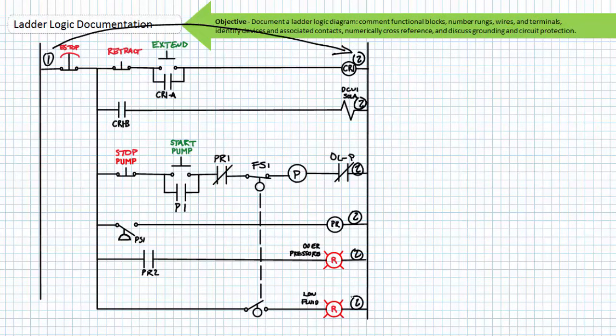All devices attached to this common connection are assigned the wire number 2. Note a number of different devices all have wire number 2 leading from them. I must again emphasize that wire numbering is better thought of as node numbering. A voltmeter from wire 1 to the terminal of any device hooked to wire number 2 should read the full pilot voltage.